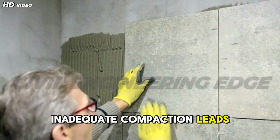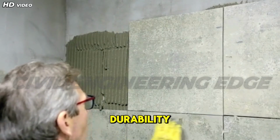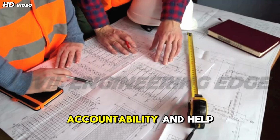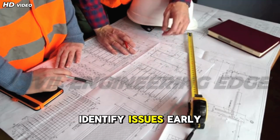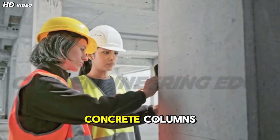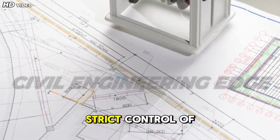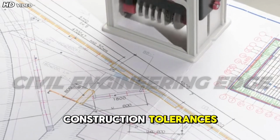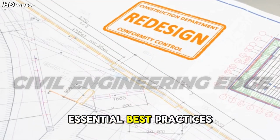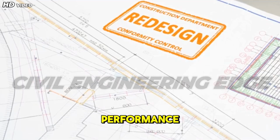Inadequate compaction leads to voids and honeycombing, which significantly reduce strength and durability. Documentation and inspection records provide accountability and help identify issues early. Regular quality checks ensure that reinforced concrete columns achieve their intended performance. In conclusion, strict control of construction tolerances, well-designed formwork, and effective quality control are essential best practices that bridge the gap between design and real-world performance.